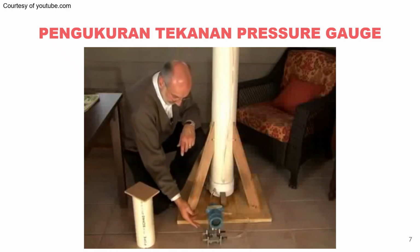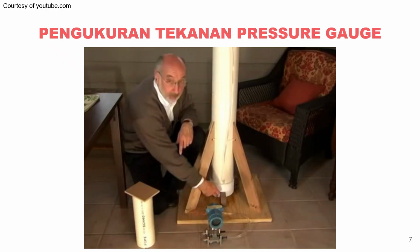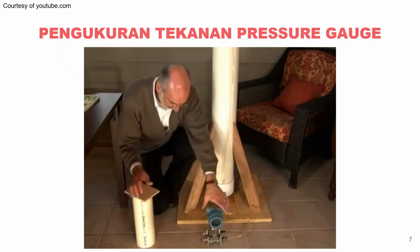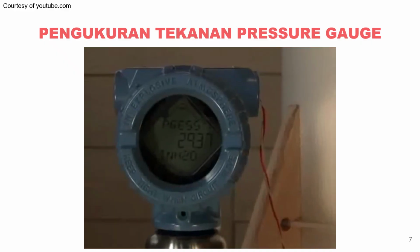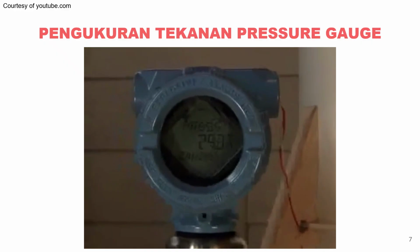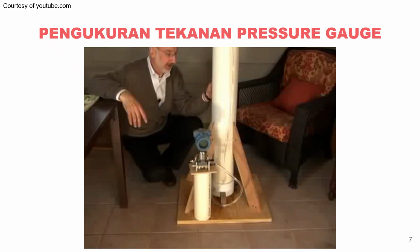As you can see right now, the pressure sensor actual element is down here, roughly equal with the bottom of the tank. But let's lift it up and set it up here. Pressure reading changes by about 14 inches. Now all this works very nicely if the tank is vented and it's open to the atmosphere and there's nothing else that's going to interfere with the actual static pressure of the weight of the water.